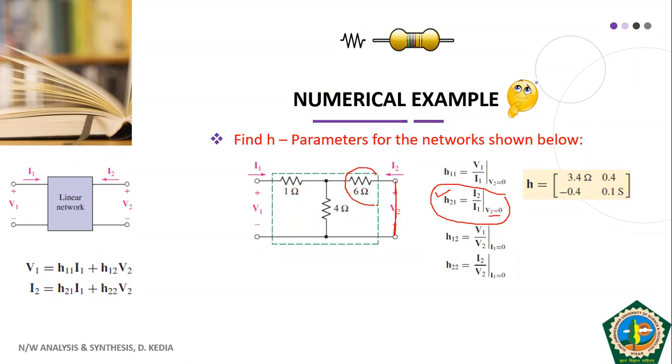We know that the current in this branch is I2. I1 is moving in this branch, and once it comes across this junction, this I1 will be divided. So in a way you can say that I2 is a component of I1, or you can say current has been divided. But there is one change here: when I1 enters this node, the direction of the component will be towards the right hand side, whereas the direction of I2 is directed inward. So I should indicate this arrow with minus of I2 instead of I2, because I am reversing the direction.